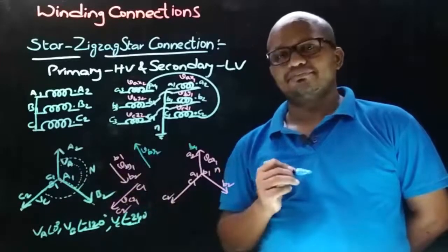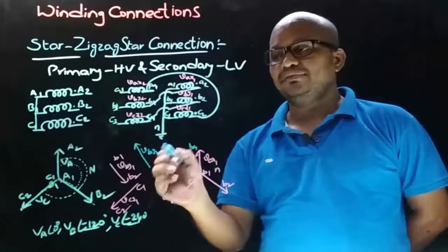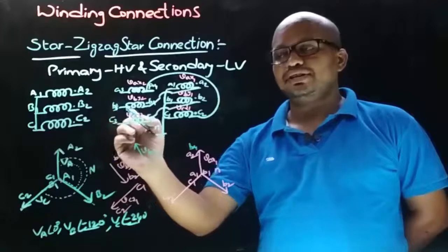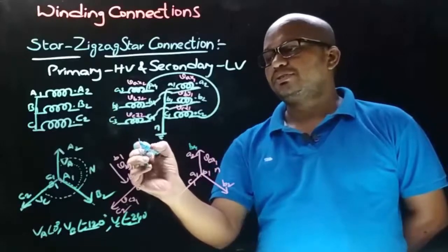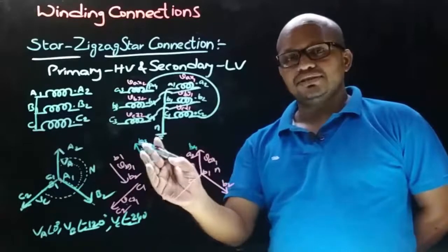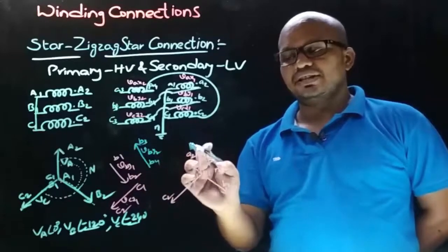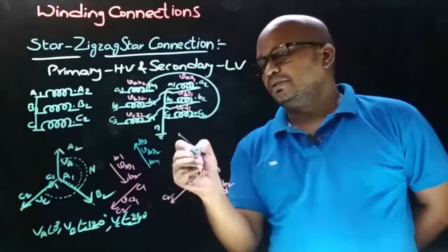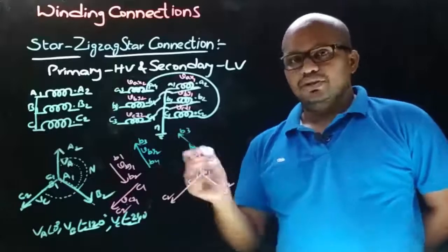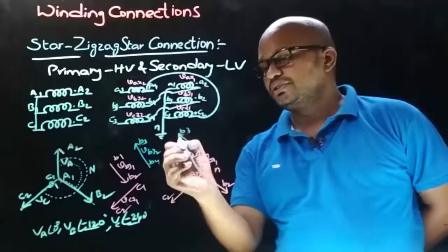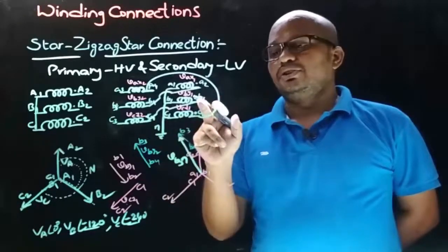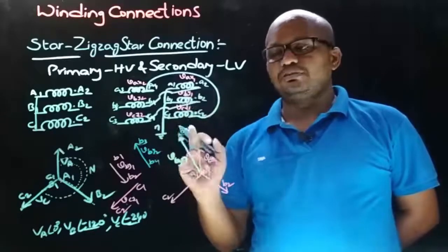So like this. Now we need to decide the terminals of secondary side VBY2 phasor. So terminals are here B3 and B4, and they consist from non-dot end, that is B3. Therefore, arrow will point towards B3 and other end will be B4. Therefore, draw this VBY2 phasor such that A2 will have B4 terminal, means like this. This is B3. This one is B4. Therefore, now the resultant voltage is VB3N.